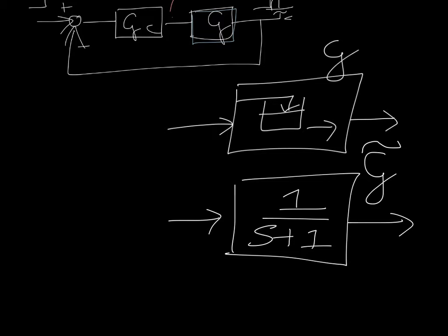And so in terms of our design calculations, the reason why we make this distinction is because we can find the forward relationship with the real plant by doing a test. So we can go onto the plant and introduce some test and actually observe what happens, right? And so that's always available to us. But in real life, the real plant does not allow us to do math on it. It only allows us this kind of forward direction calculation.